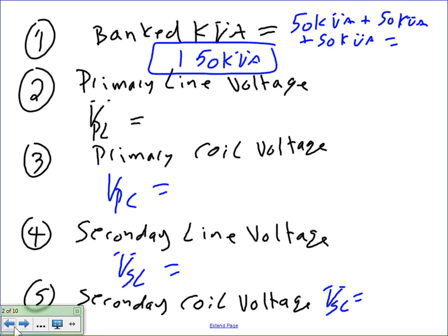The coil conductors. Don't you have to have a larger one for a delta, because you're running the current through all three transformers? Good point. The coils inside the transformer are rated to handle a delta connection or a Y connection. Very good point, though.